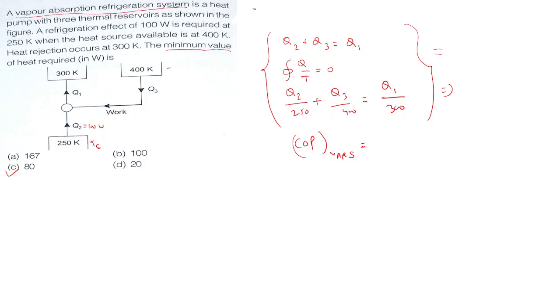So here this is the evaporator and this is the generator, right? And this is the environment. So what is the formula like? TE, TG, TO by TG. To remember the formula, just remember it as "ego by go e". By this way you can remember. Right? Once you have that, just put in the temperatures and see what the COP would be. Anyone calculated this way?